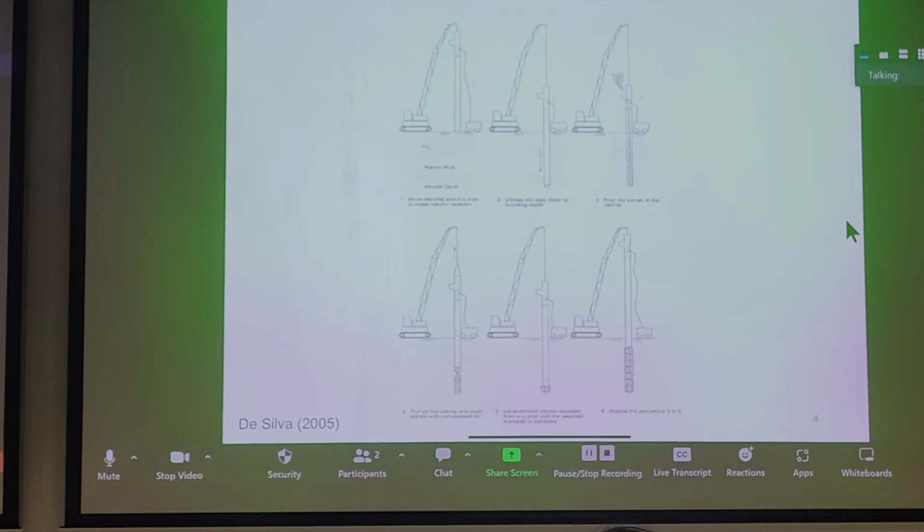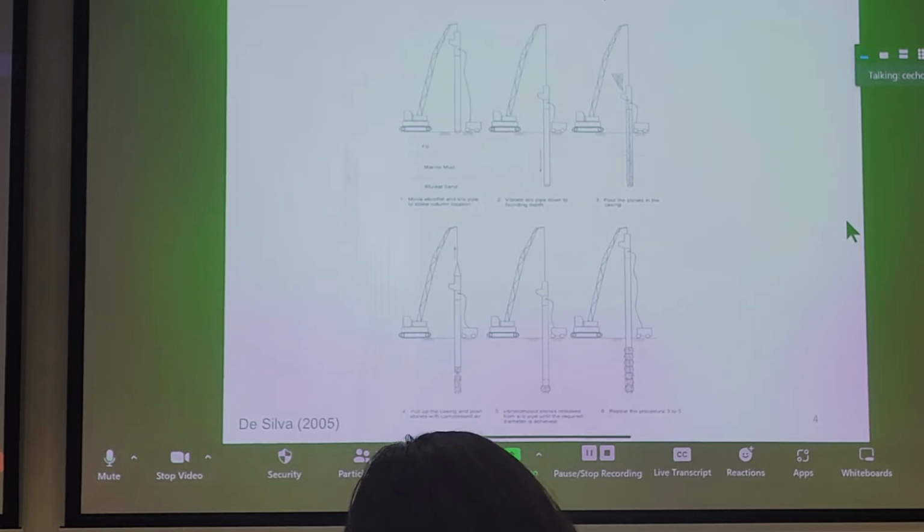For this particular case, we already looked at different types of deep replacement methods. In this case, they use bottom dry feeding, particularly with gravel material. And before you can carry out deep replacement, you have to do trials. You might be thinking, what does a trial mean? Well, they had to do a bit of trial and error to see how much power they needed for this vibration device, this vibroflot, to get it into the ground to the target depth.